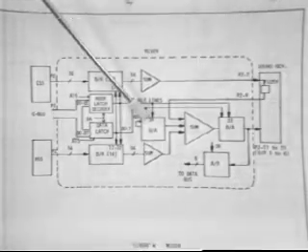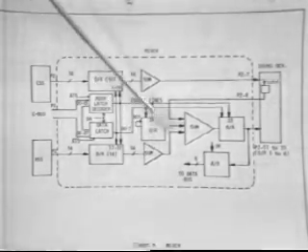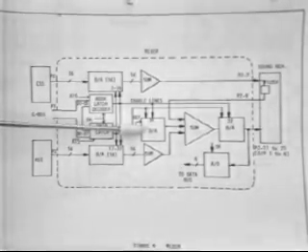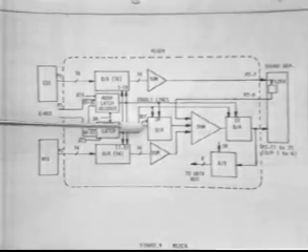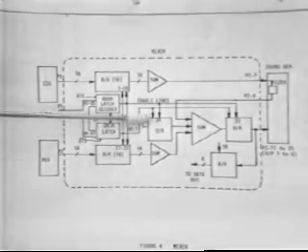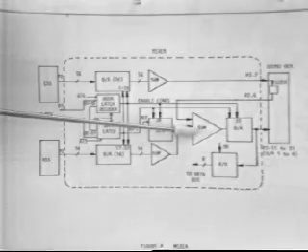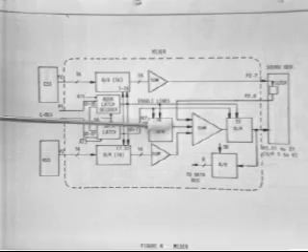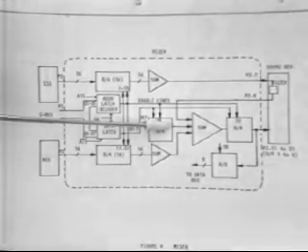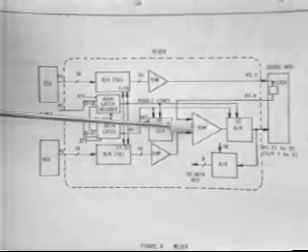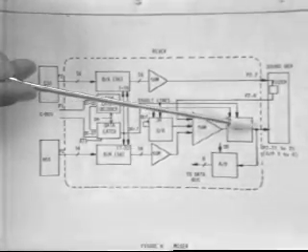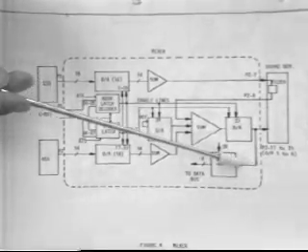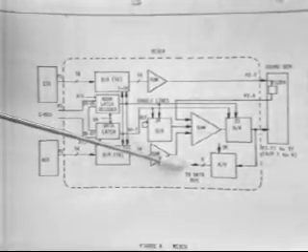Now you'll notice here right in the middle, there's one D2A that is all on its own. It gets its signal from a voltage reference out of the D2A, back in and into the summing amp. And this one will be enabled only when I am testing this card. It will be feeding the signal on its own to the tie point past the last D2A, down to an A to D, back to the C bus.